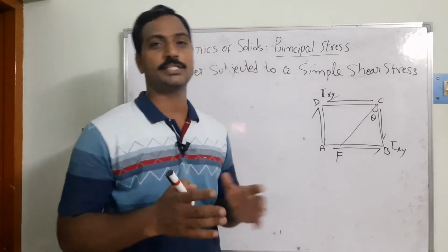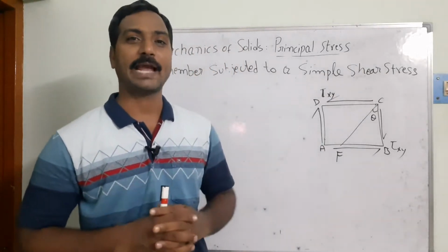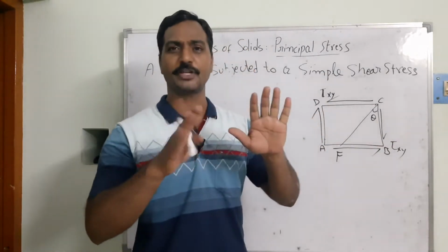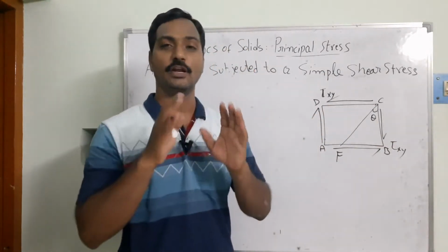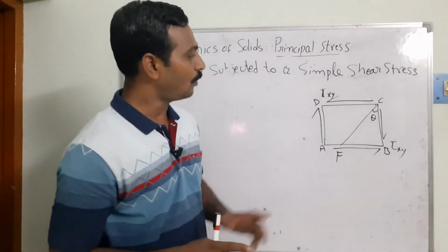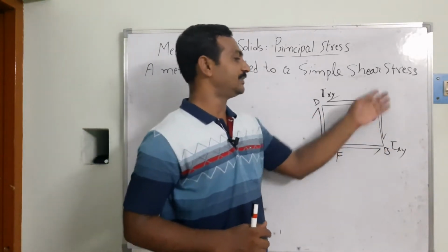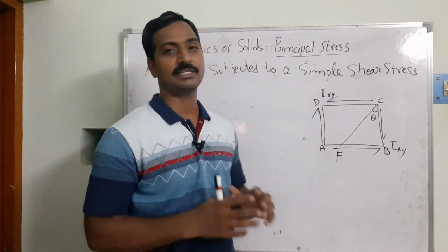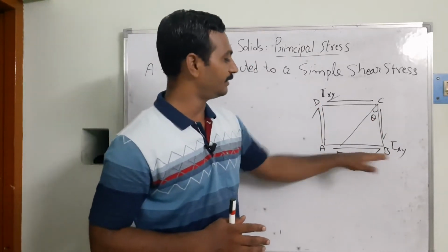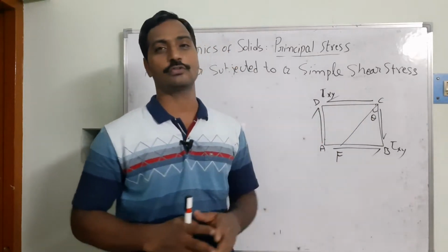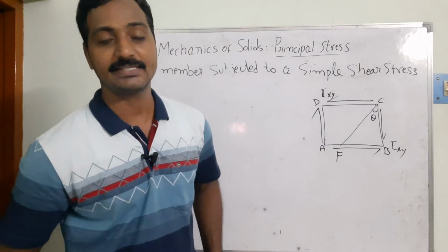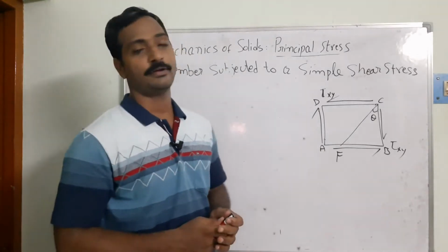In the last video lectures we have seen the normal stresses acting on the member. That's going to be ABCD, a two-dimensional element. It has its own thickness, which we have considered to be unit. Now we subject these faces to stress. BC and AD are subjected to the same magnitude, and AB and DC are also subjected. Here the tau xy I am going to consider is the shear stress acting on your face BC.